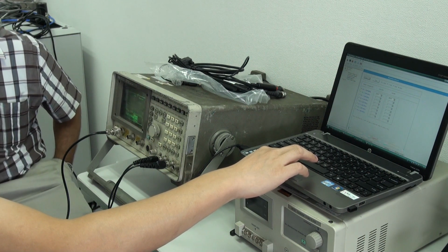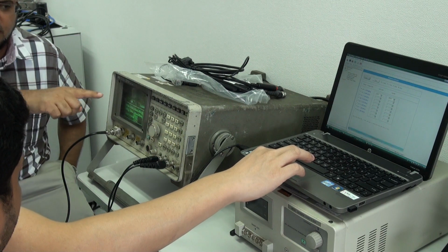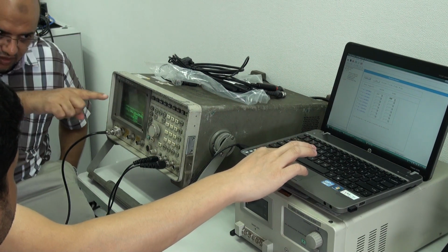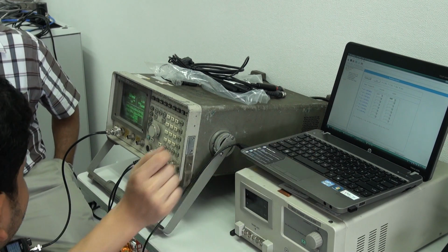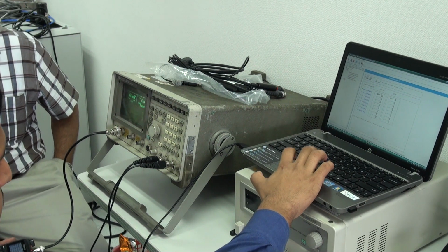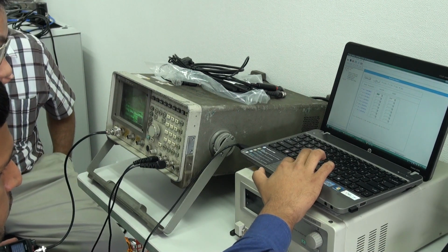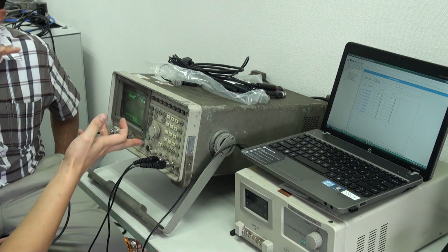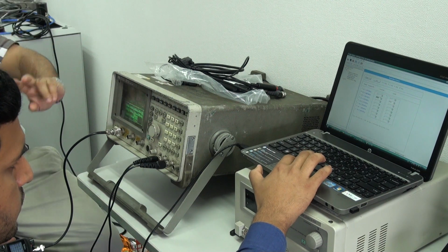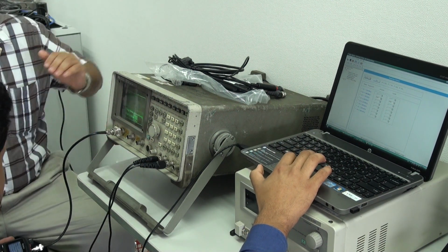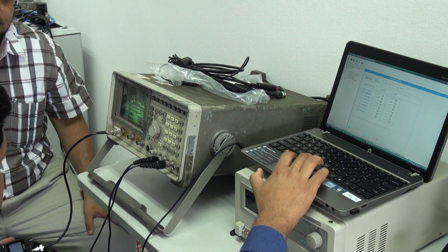Increase the deviation a bit and it will adjust it. Keep the low at 5 and the high? Is that right? It should always be 5 kilohertz here for the deviation. Send the high and send the low, then go to another one and see the difference. Whether it is low power or high power, the standard is the same. Turn me 5 on. Send low and send high, and this should be all the time 5K, right? It must be 5.